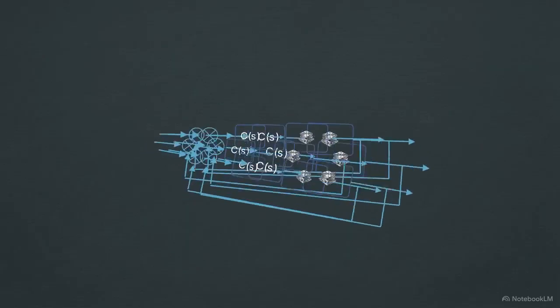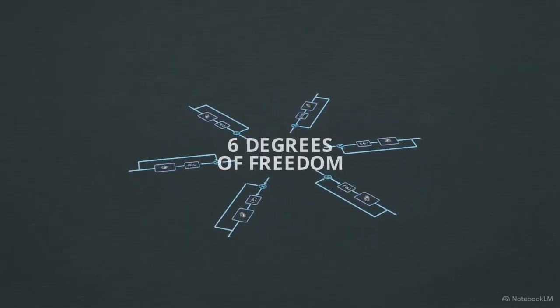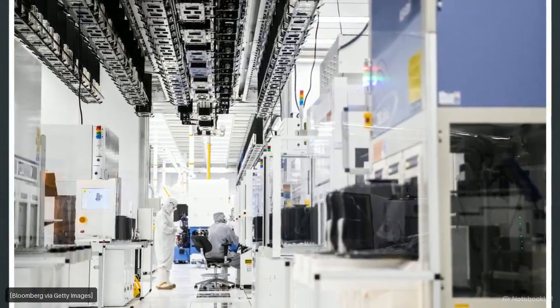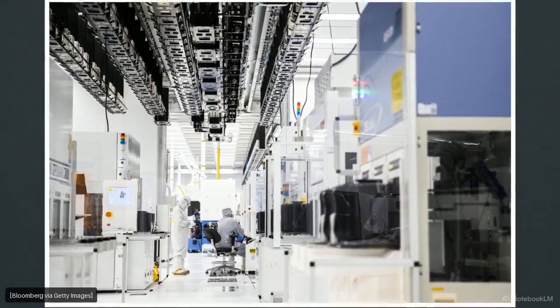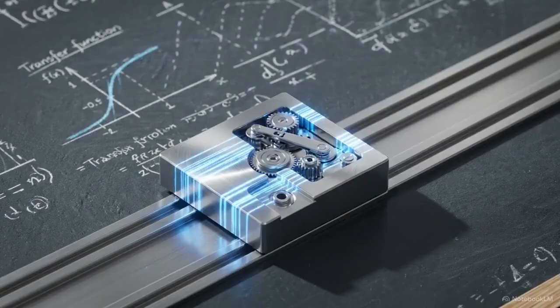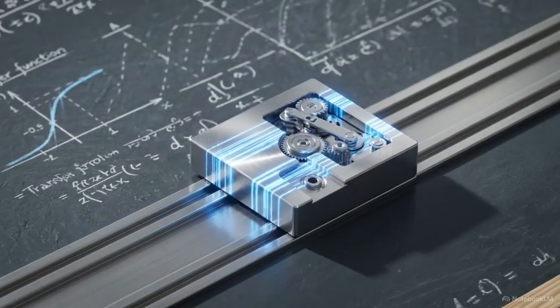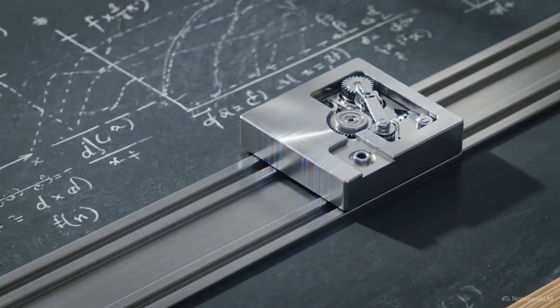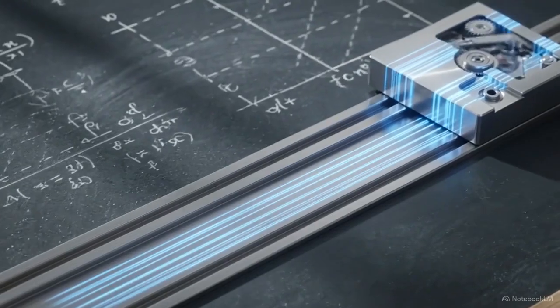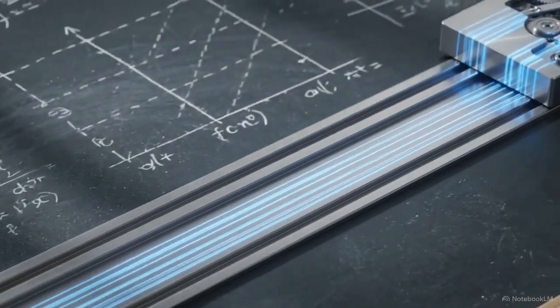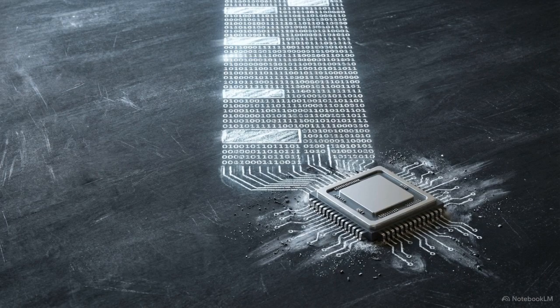The math we just outlined solves a single axis of motion. Inside the actual cleanroom, the ASML wafer stage is a 6 degree of freedom multi-input, multi-output system. Every single axis is tracked by position sensors accurate to 60 picometers, taking readings 20,000 times a second to feed the closed-loop controllers. That sensor density generates 31 terabytes of raw data per week from a single machine, routed instantly back into the control algorithms.